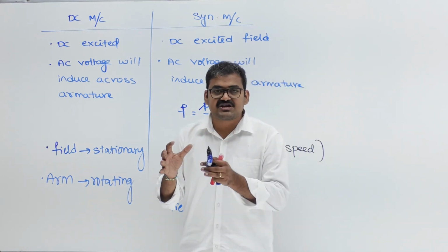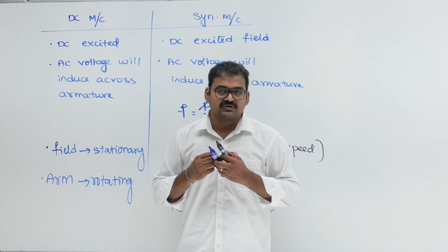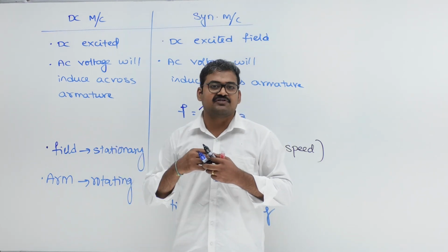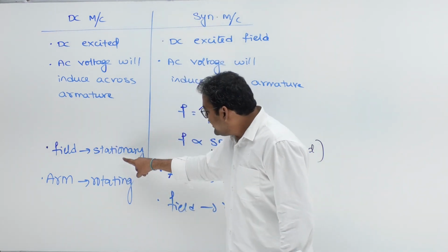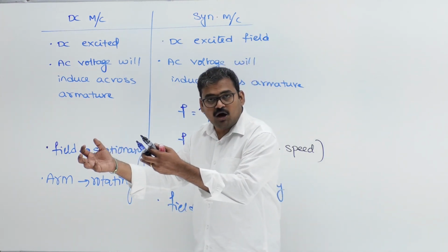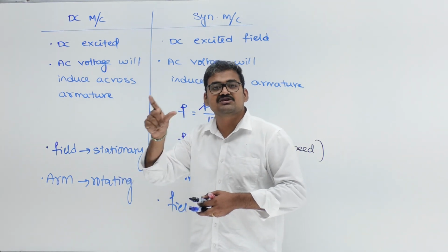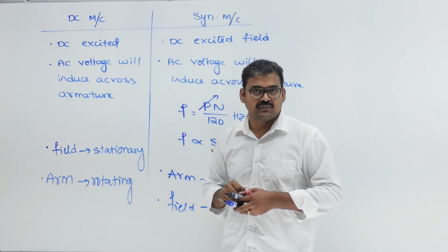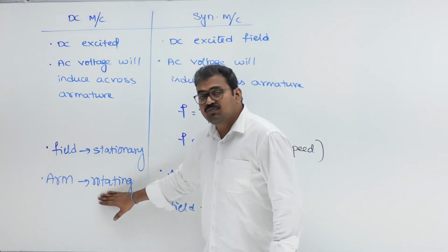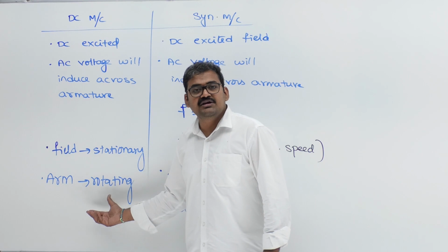When winding is stationary, it is always very easy to collect the current from the winding. But when the winding is rotating, when armature is rotating, collecting the current out of a rotating part is very difficult. Always arcing and sparking problems will be there. Even though arcing problems existed, why are we still using rotating armature winding only in DC machine?